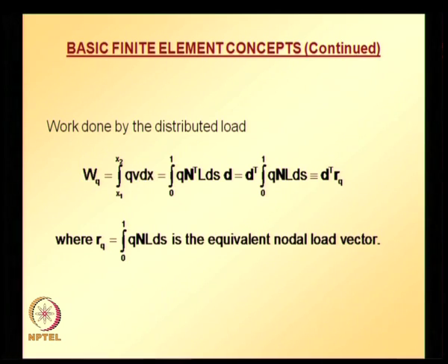Even if q, the distributed load, is a function of x or a function of the spatial coordinate, that can be included inside the integral and integrated, which gives the equivalent nodal vector. So the previous equation and this equation are general equations which are applicable even if E, I and q are functions of the spatial coordinate.